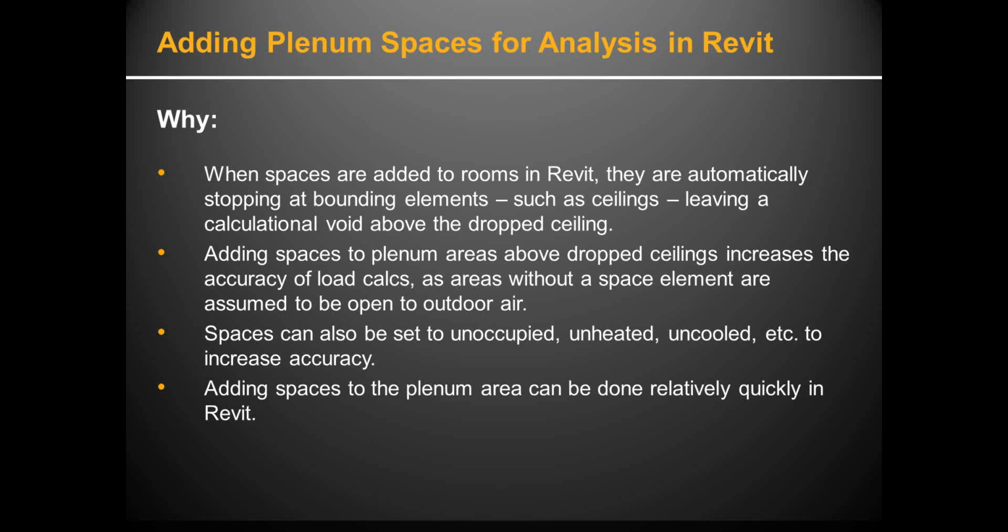So that's what we're going to do today: we're going to add those spaces in the ceiling, above the ceiling in the plenum, so that we can use those in the load calcs. And by having those in there, it increases the accuracy of your load calculations, because areas in a building information model that don't have the space element are just assumed to be open to the outdoor air. There's just no data there. Well, it must be outdoor air.